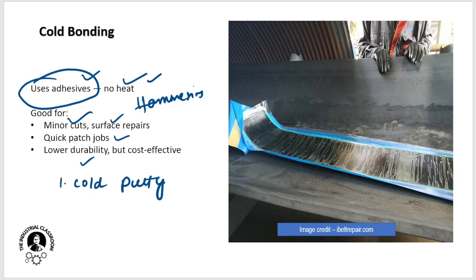Now this is a repair strip. It is a type of rubber, a conveyor belt top cover, you can say, which is a rubber material. What they will do is apply solution on the place of the conveyor belt where they need to fix it. After using 2 to 3 coats, they will generally put the repair strip here and then remove the plastic. So they will overlap it here and then remove the plastic, or keep the plastic. These plastics are generally kept to ensure that the rubber is not damaged. After doing the repair work, we remove the plastic.